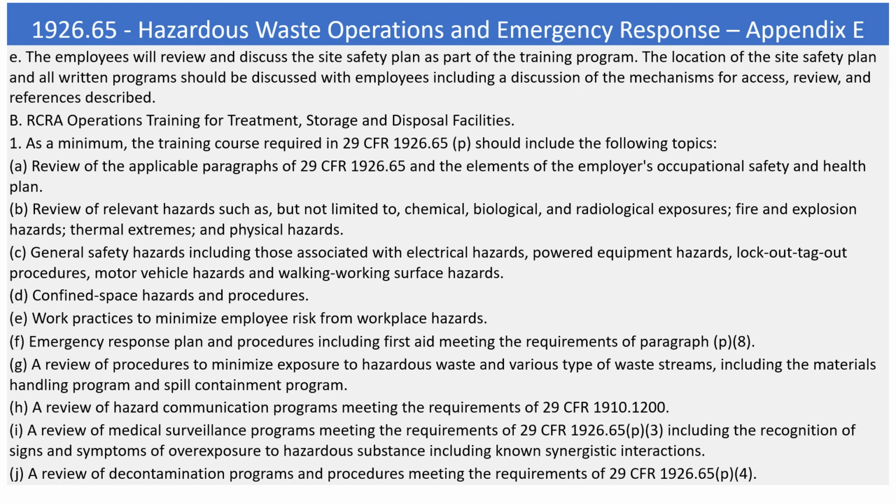C. General safety hazards including those associated with electrical hazards, powered equipment hazards, lockout-tagout procedures, motor vehicle hazards, and walking working surface hazards. D. Confined space hazards and procedures. E. Work practices to minimize employee risk from workplace hazards. F. Emergency response plan and procedures including first aid meeting the requirements of paragraph (p)(8). G. A review of procedures to minimize exposure to hazardous waste and various types of waste streams, including the materials handling program and spill containment program.